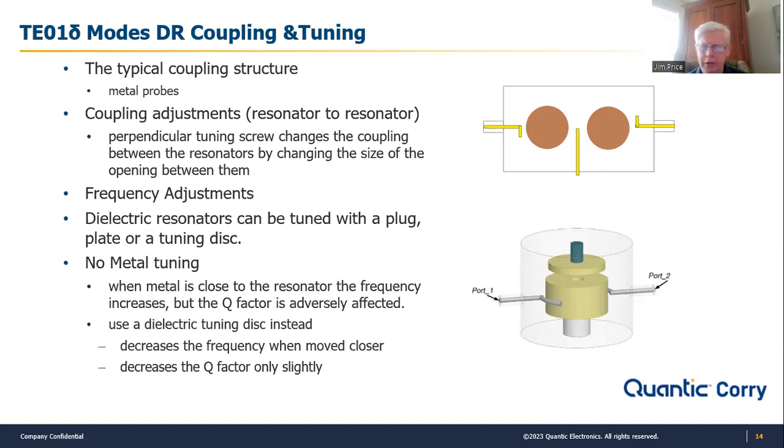And then to tune the resonators, you can see on the lower one, you can bring in, in this case, dielectric material that's the same as the resonator material closer to or further away from the top of the resonator. And that allows you to adjust the resonant frequency, the center frequency of the resonator. So that doesn't have anything to do with how much energy is coupled into it or out of it, but it rather sets the resonating frequency of the resonator itself.